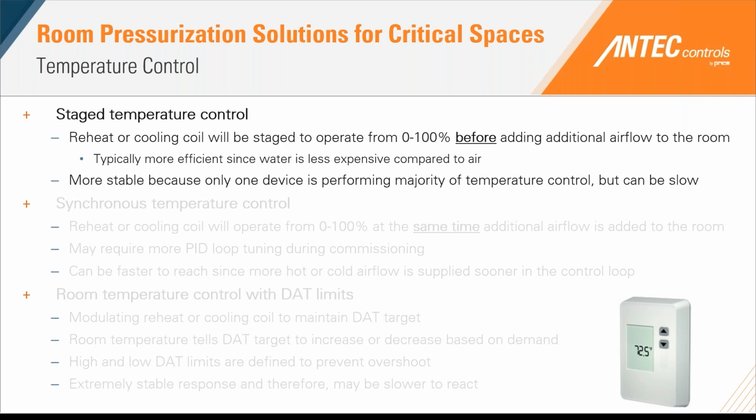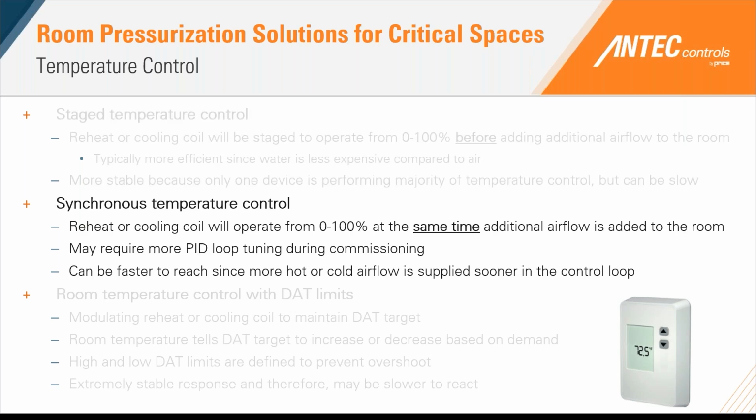So if you do have applications where you have a large number of thermal equipment that can be turned on and off at once, or if you have a space that's facing potentially exterior windows where you can get a large swing in thermal loads when the sun is shining, you may want to consider a synchronous temperature control approach.